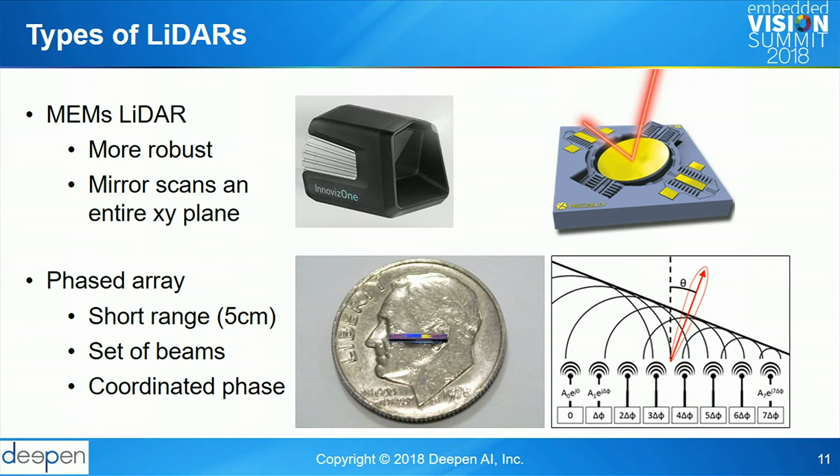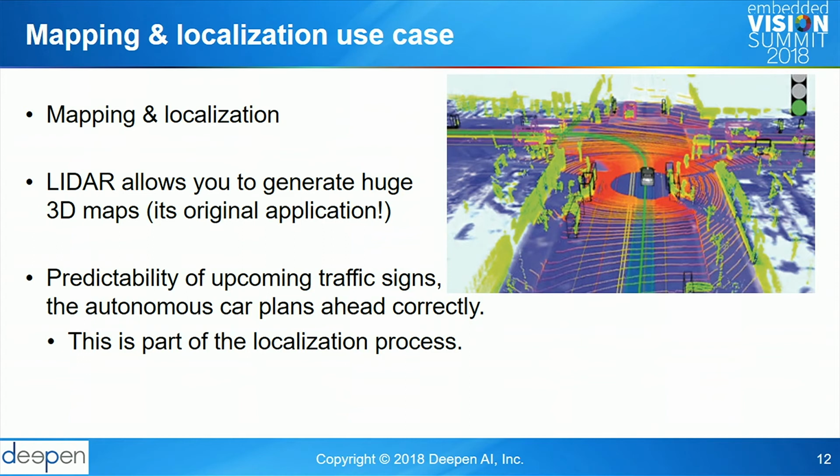Cool, so use cases. Most of the autonomous driving companies today are actually not using LiDAR for perception. Most of them are using it for HD mapping and localization. And what they do is they go offline, collect tons of LiDAR data, form very dense point clouds of the streets that they want to drive in. And then in the production vehicle, when it's driving, it tries to compare the point cloud it's generating as it's driving to the point cloud that is stored on the vehicle. And they use that to measure the deltas to see, am I really on El Camino? Am I really on 101 next to this intersection?